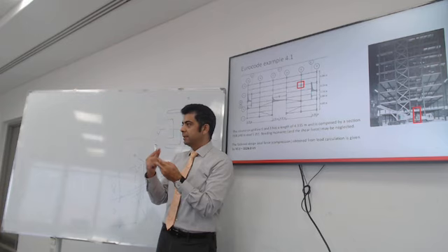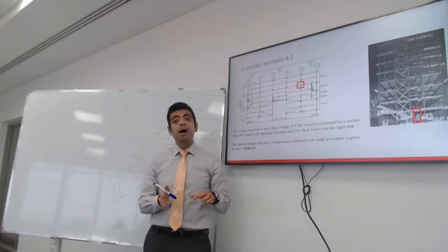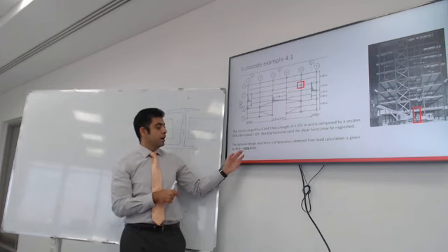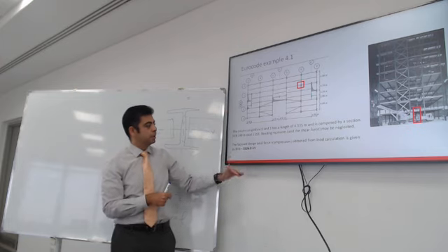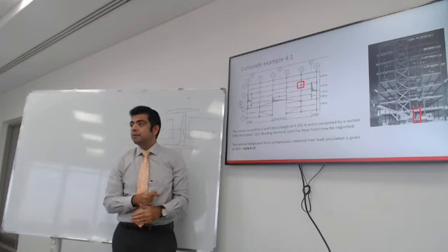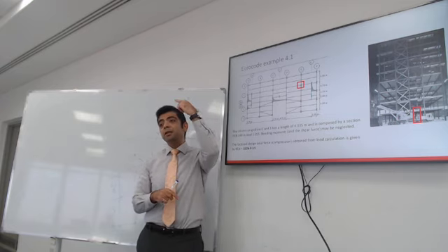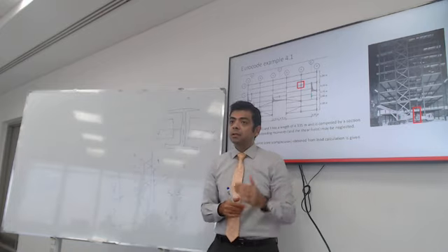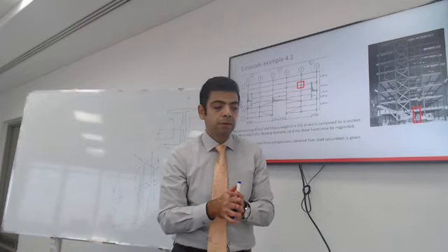You get the self-weight, the dead load, and the live load. You use the factors, 1.35 dead, 1.5 live, and then you figure out the axial load. That's the axial load: 3326 kilonewtons. So it is supporting a lot of load. It's probably because it's a multi-story building, so the load accumulates. The columns at the bottom will have a lot of load, while the column at the very top is just supporting one level. So you don't have to use the same section for the entire building. Every so many floors, you can reduce the section a little bit to be more economic.